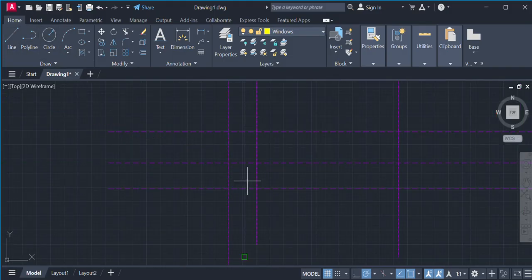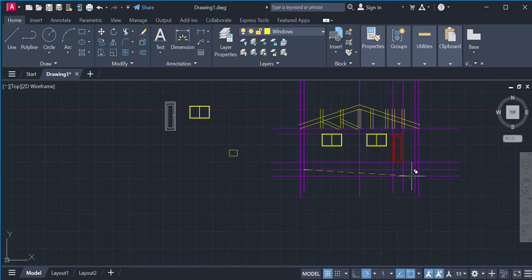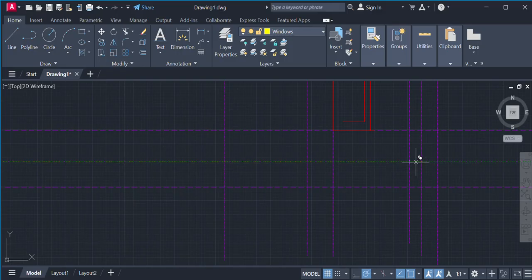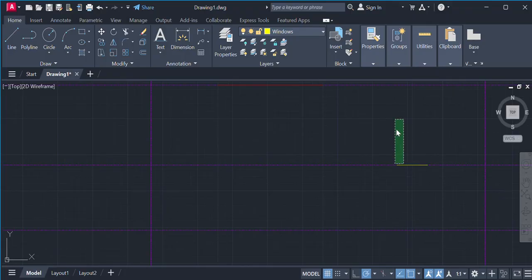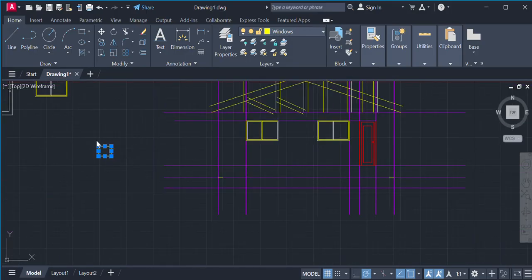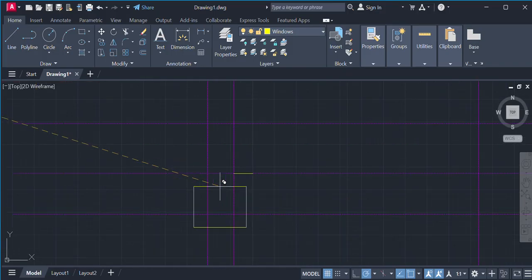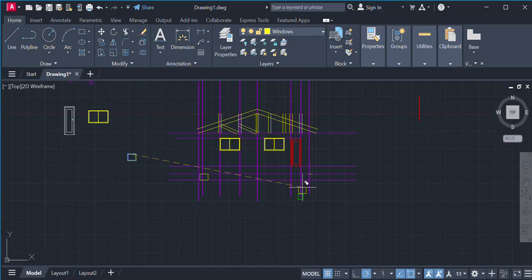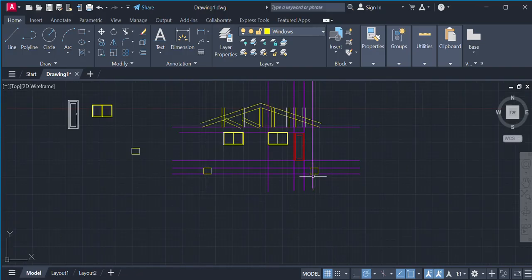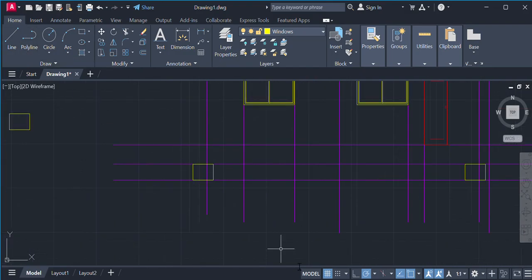There is no midpoint. I hate it when this happens. Just construct a mini line, copy it to the other side as well, so you have an actual midpoint to snap to. Remember, it's really hard for this thing to snap if there is no midline or midpoint. So you create a mini line that will essentially represent its midpoint. Now we can copy. I know, this looks like a lot of work, but okay, and the rest of it will be a wall.